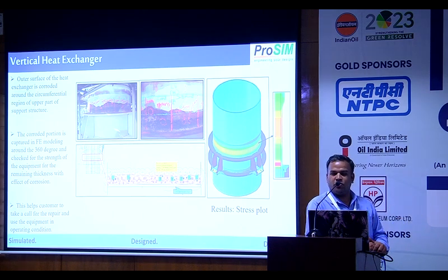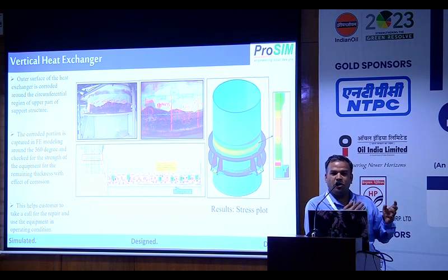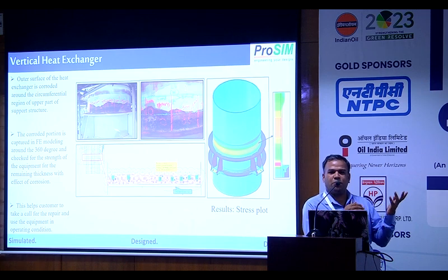The nominal thickness is around 27 mm. The asset integrity team captured the data grid-wise, over the overall 360 degrees, measuring the remaining thickness. On the west side, there was already 7 mm depth of corrosion, somewhere it was 12 mm, somewhere 8 mm. So how do I bring that physical model to the actual mathematical model in the numerical method? That is the most challenging. By capturing each grid cell with the remaining thickness of the shell over the ring support, we capture these parts one by one. Again, the temperature was around 350 degrees Celsius.